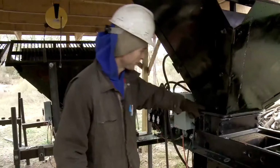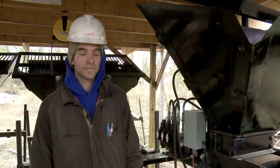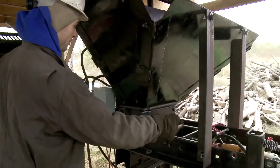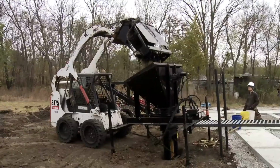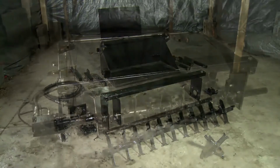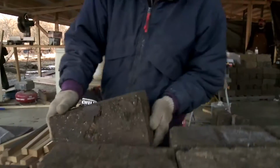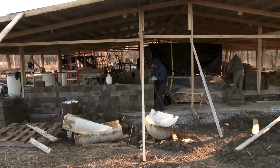The basic design of the machine is a compression frame. So you start with that frame, which basically is this part from here to there, and the rest is everything that supports that compression. So you've got the secondary cylinder that moves a drawer in and out to load soil. You've got a huge hopper that can be loaded with a tractor. We are the only CEB pressing operation that does this, which means a device that pulverizes and loads the soil in one step. If you use double CEB walls with straw bales in between, that's a hybrid CEB straw bale construction. That, to me, could perhaps be the next generation of housing for humanity.